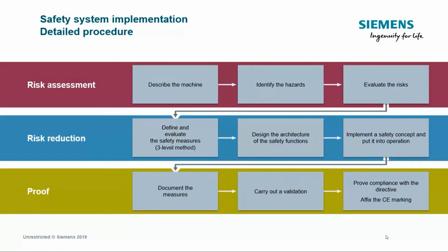And based on that assessment, if you find that there are, say, unacceptable levels of risk, then, based on some criteria, you define what kind of safety system or safety device you need to use. For example, as a simple measure, there is some rotating part that can cause injury to someone operating the machine. As a simple measure, you can just put a cover on that rotating part, and then you reduce the level of risk to an acceptable level. So then you can have your machine operated in a safer way.